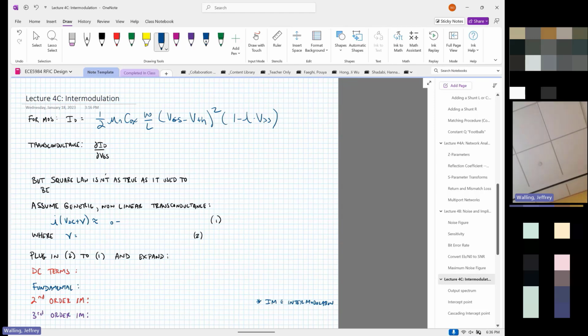All right. But we can take some clues from this anyhow, and we still do use these principles for a table-based design. So we care about the transconductance. Transconductance we define as dID by dVGS. So the ratio of the change in current I get for a change in control voltage, which is the gate to source voltage.